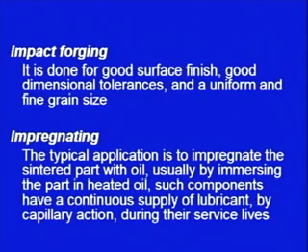Then we can go for impact forging. What is impact forging? Impact forging is done for good surface finish, good dimensional tolerances and a uniform and fine grain size. So if we want good surface finish, good dimensional tolerances, and if the grain size required is fine, then we may go for impact forging.